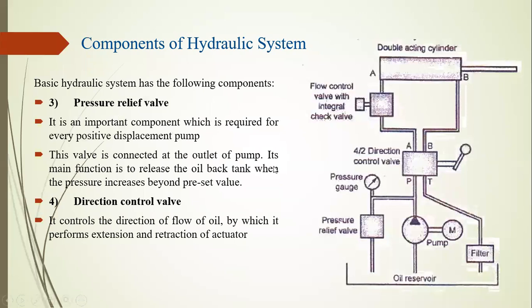Then, another component we have to show is a pressure relief valve. This portion is the pressure relief valve. It is an important component which is required for every positive displacement pump. When we use a positive displacement pump, it gives a continuous flow inside the hydraulic line or hydraulic circuit. Whenever the hydraulic system is closed, or it may be set down or in a stop condition,